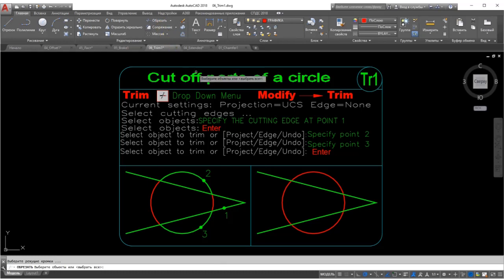Step 1. Click the Trim or Extend button on the Home tab's Modify panel. AutoCAD prompts you to select cutting edges that will do the trimming, or if you choose the Extend command, boundary edges to extend to.